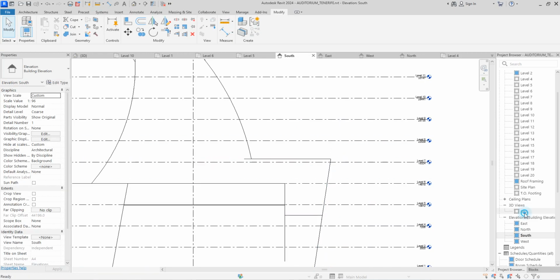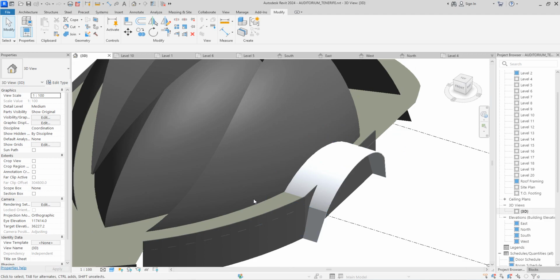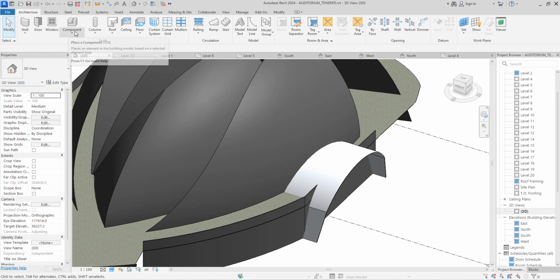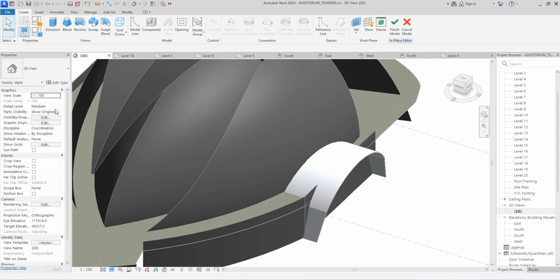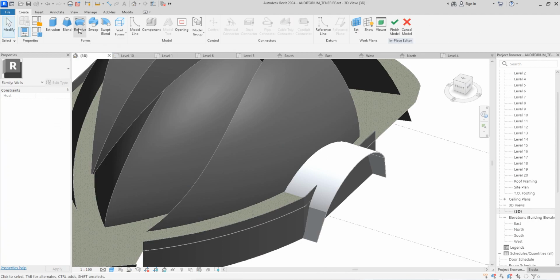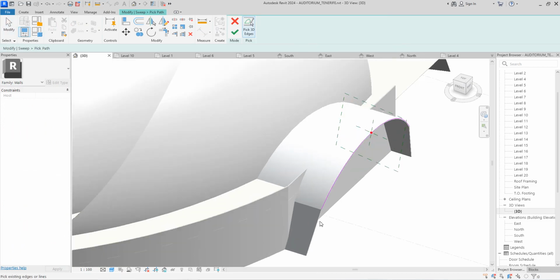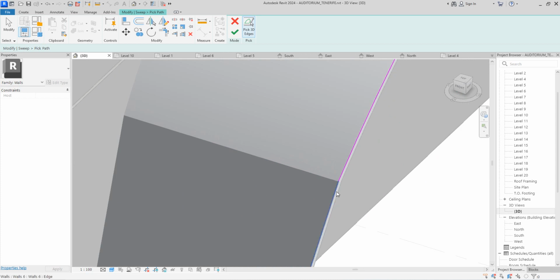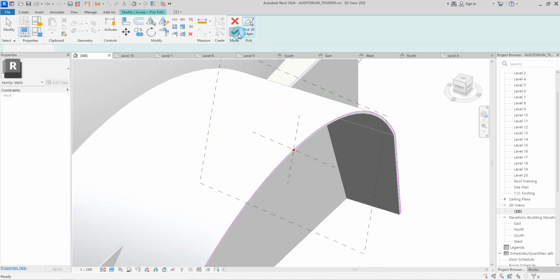So go back now and do the needful. Instead of having the bending edge, it's going to be straight up. This part is what causes the whole problem. So go back there and say component model in place. Come to wall, select the wall, pick, say 707. Then you come to sweep, and the sweep pick. So I think it's in the middle now. You shouldn't have any problem again with what we are doing. So select that and you say finish.